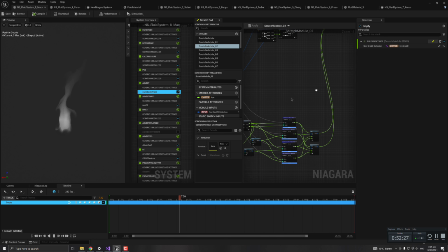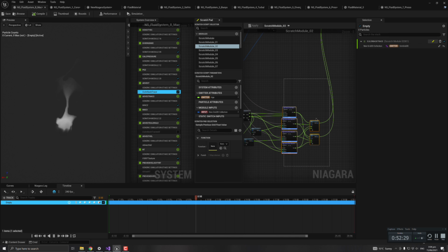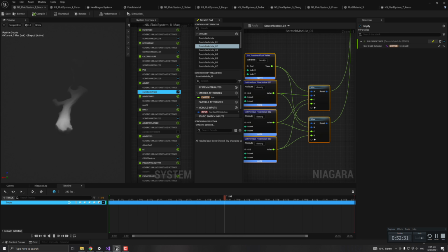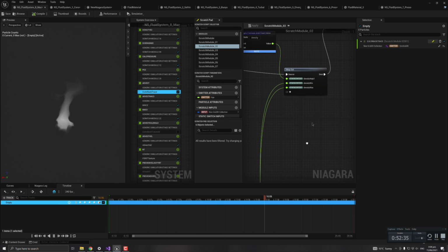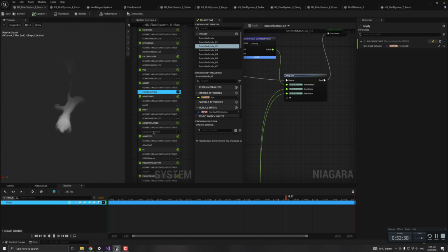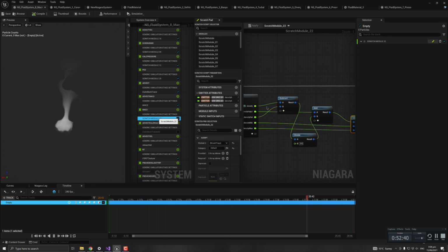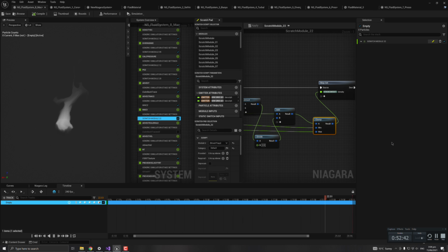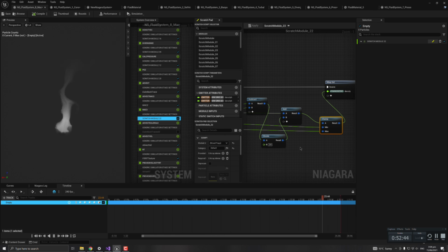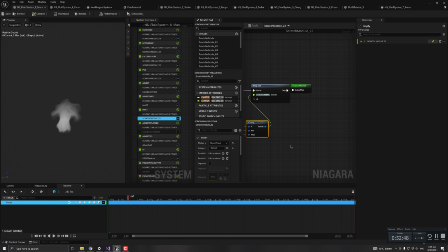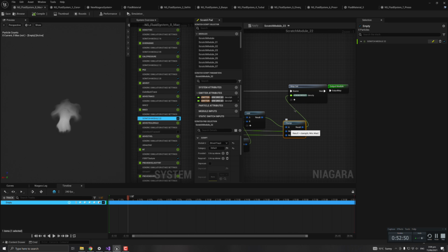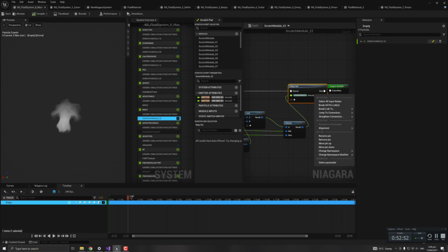It's just that in this case we're storing the min and the max of those 4 voxels, and we just store them in 2 different channels, which we can reference later. And I will just come back to here. So you read those clamped values in and just do a clamp at the end and write back to density. And that gets you much higher detail solves. Otherwise it can get quite dissipative.